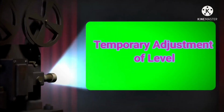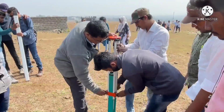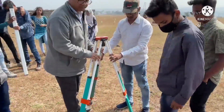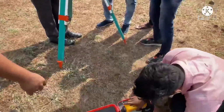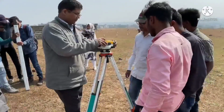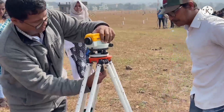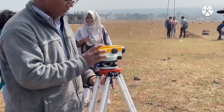Okay, so now after doing the grid formation, we will move further for temporary adjustment of the level in order to carry out the fly leveling operation. Okay, so in which we will first open the tripod legs at a suitable height, spread them equally on firm ground, take the auto level from the box, and fix it with the help of the wing nut.